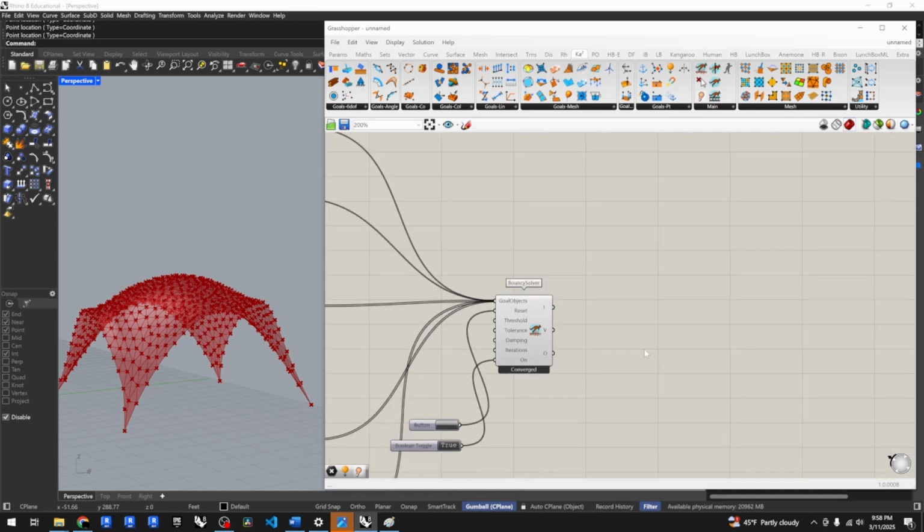If I just want to filter out certain elements, one way is to make a container for that, but we'll see that we're feeding in a whole list of items. It's not very happy about that. It is getting the mesh, but there's a whole bunch of null items for everything that wasn't a mesh within this list. So the other way to go about that is List Item.